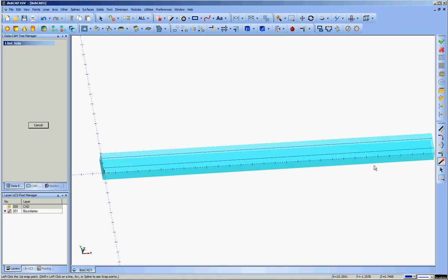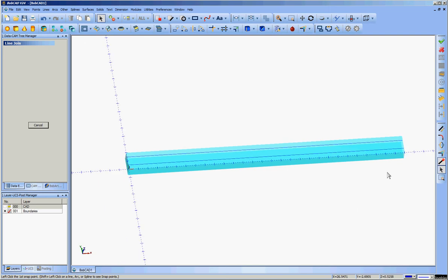Then I'm going to use line join to just make a rectangle. Okay. So the boundary is basically a fence, and it tells the system to keep the toolpath within the fence. If you tell it to cut inside there, you can also put some geometry in there and it will not cut into that geometry.